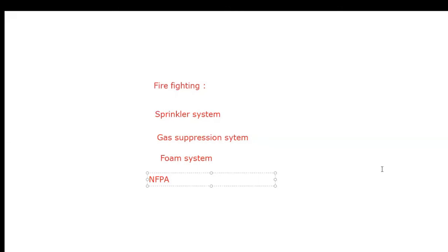When we are providing this sprinkler system, especially for a commercial office building or an IT industry, what happens? If there is a fire within the building, especially in server rooms, this sprinkler system is going to control the fire within the designed span of time. But the major issue is that at the same time, water will spread everywhere within the space itself. So we may lose our assets also, or there will be a huge loss for the building. If we lose our assets like our computers or valuable documents, then it is a major drawback of a sprinkler system.